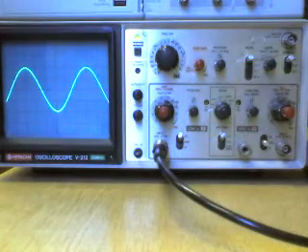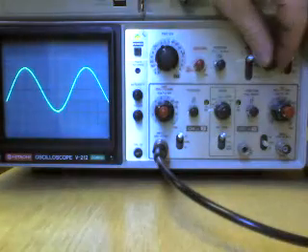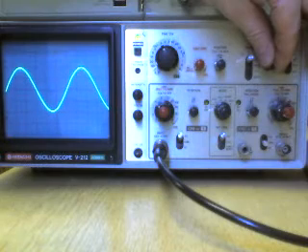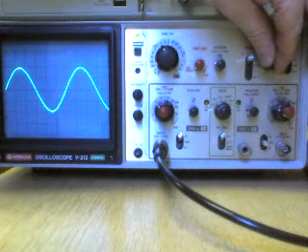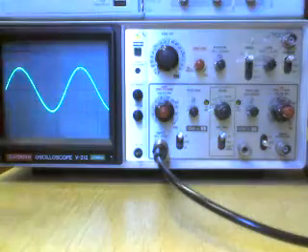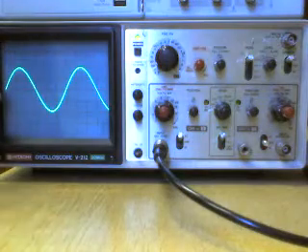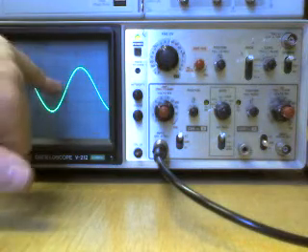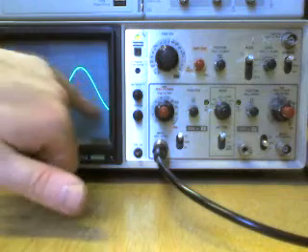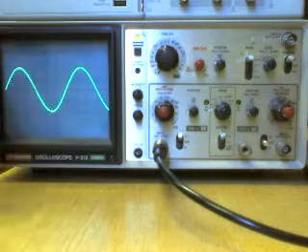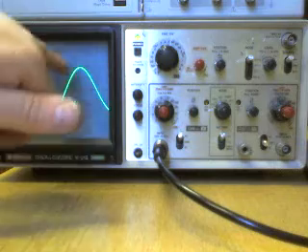Okay, so the waveform stabilizes, and you can tell it to trigger at the center of the sine wave, so it actually starts at 0 just like a normal sine wave does, stops at this point, starts again, goes off the screen slightly, and then it's back to the beginning and starts sweeping again.